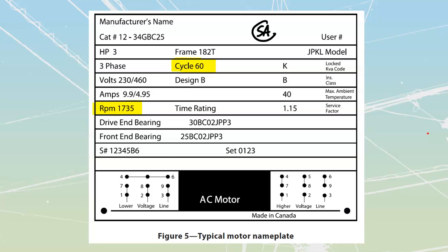And from that RPM, later on I can take this and say, hey, what's the closest 60 multiple? I know that it's going to be 1800 RPM. And from the 1800 RPM, I can then infer things like the number of poles, etc. This is how fast the magnetic field is spinning. This is how fast the rotor is spinning, trying to catch up to it. We'll cover that stuff later on, but it allows me to make a relatively decent jump from one to the other. They are directly related, meaning that if my frequency would change, my RPM would change as well.